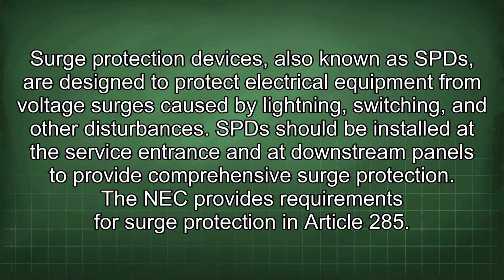Surge protection devices, also known as SPD, are designed to protect electrical equipment from voltage surges caused by lightning, switching, and other disturbances. SPD should be installed at the service entrance and at downstream panels to provide comprehensive surge protection. The NEC provides requirements for surge protection in Article 285.